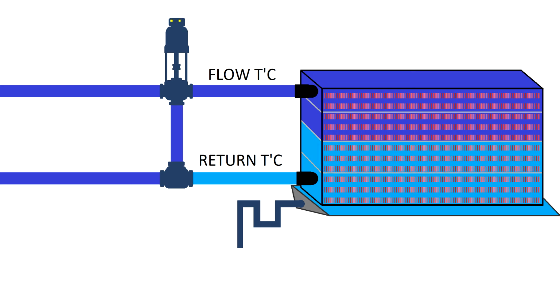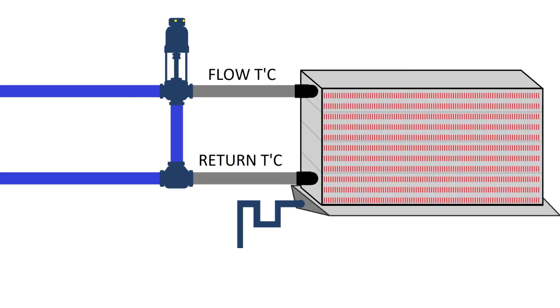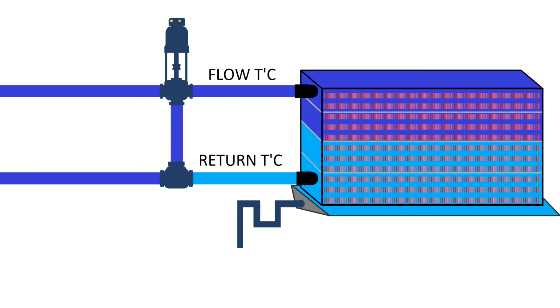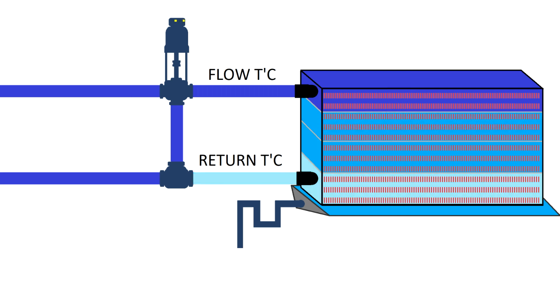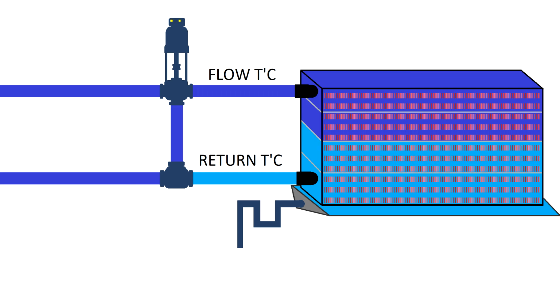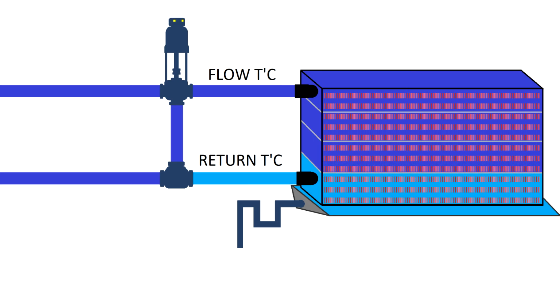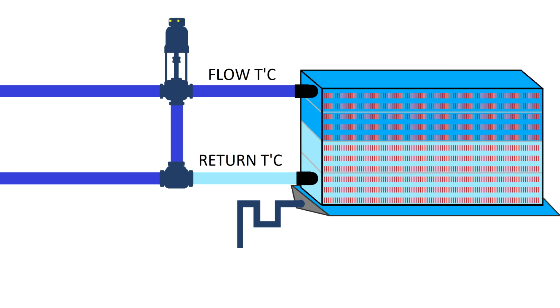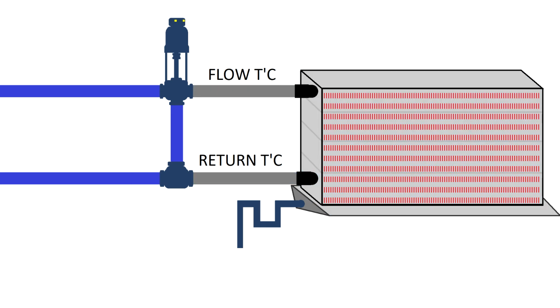Now it is very important for you to know the glycol temperature, the way the temperature has been designed to be. Imagine you have a variation on glycol temperature. Now the actuator will try to compensate. If the cooling heat exchanger will not be cold enough, the actuator will open 100%. But even like that, the heat exchanger will not reach a lower temperature, and its performance will be pretty badly diminished by the cooling agent temperature.